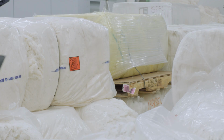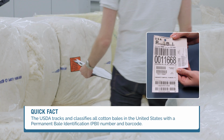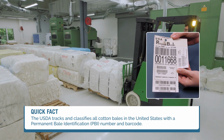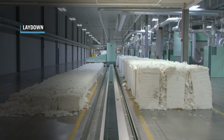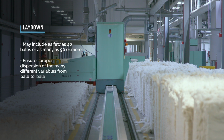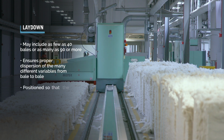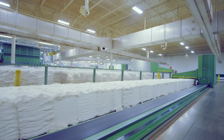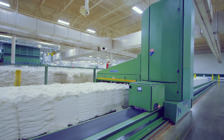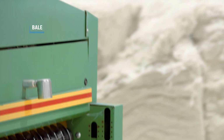After the appropriate fiber properties have been decided on, the selected bales are prepared and arranged for their placement into a laydown. A typical laydown may include as few as 40 bales or as many as 90 or more. This configuration ensures proper dispersion of the many different variables from bale to bale and also places them in a position that the top feeder or bale plucker can use them. Usually this is in a linear fashion, but other methods of feeding may also be found.